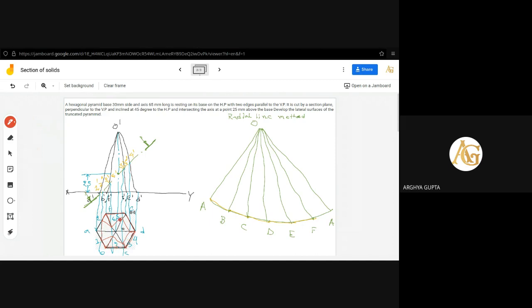Now all the points, 1 to 7, have to be marked here. Now how are they drawn? Just follow my method. Okay. So all the points will have to be projected on the true length. As point 4 is already on the true length, just take the length between O dash and 4 dash and cut it on the D point. Okay, so I have taken by pencil compass the length O dash and 4 dash. Then we have cut it as it is on D, so we have to mark the point on D only. Okay, so that point will be 4, let us say suffix 1.